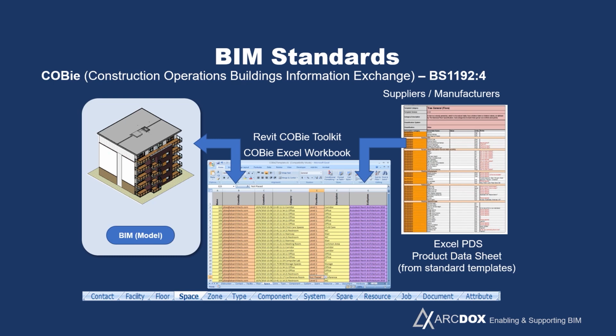So as I said earlier, some of the information will come from product suppliers and product manufacturers, and they may not be using a 3D process themselves, but what you can do is issue them with a structured electronic product data template in Excel format or equivalent, with the right attributes that they need to populate with the right values, and then, because it's in the same structure, you can import that information into the final COBie deliverable, or using tools like Excel Link or Dynamo, you can move those attributes into the objects within the model, if you like, to close the loop.